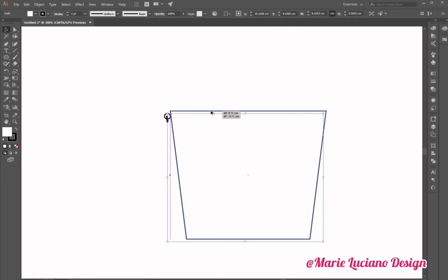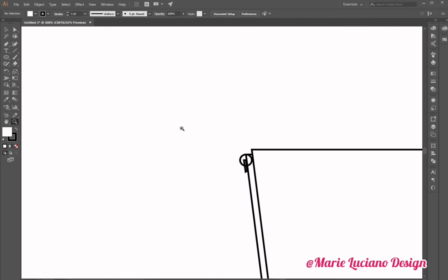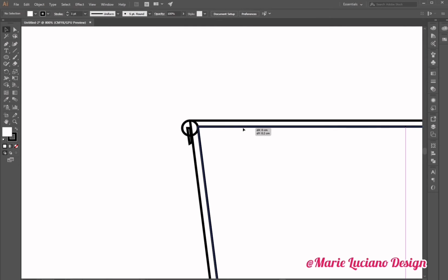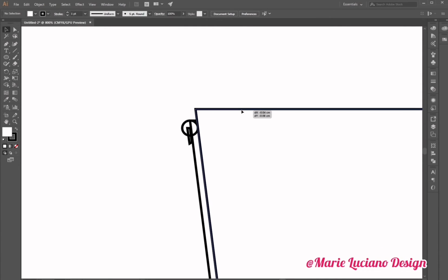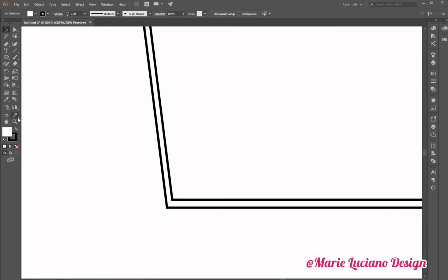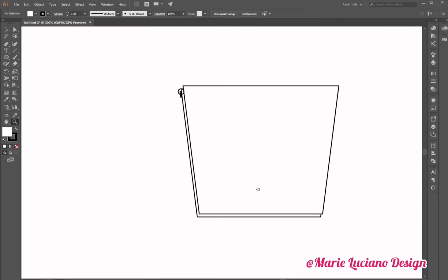So now I'm going to drag while making a copy, just the base shape, and I'm going to align it with the outer part of the circle here. I'm designing all these shapes because later on when we're done we're going to merge, subtract, and make our base shape for our 3D simulation.